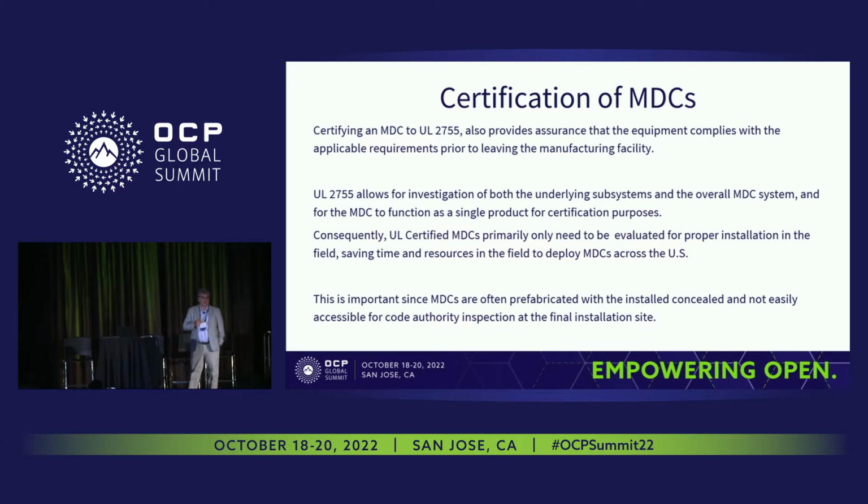Certifications of MDCs. As I said, MDCs do not have to be certified as long as you comply with every single section of Article 646 and associated articles of the NEC code. However, certifying an MDC to UL 2755 provides assurance that the equipment complies with applicable requirements prior to leaving the manufacturing facility. We know that they're prefabricated. Many of them are pre-populated.